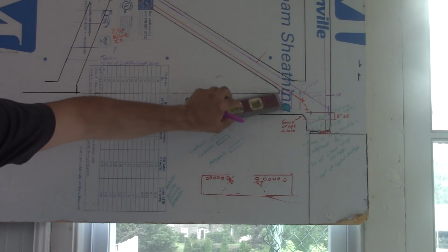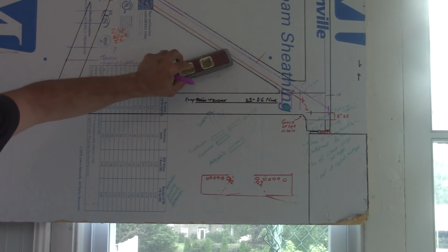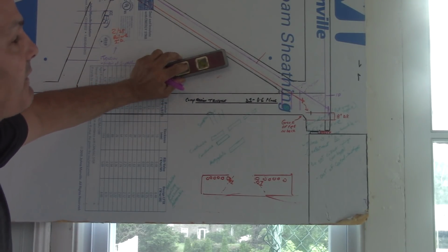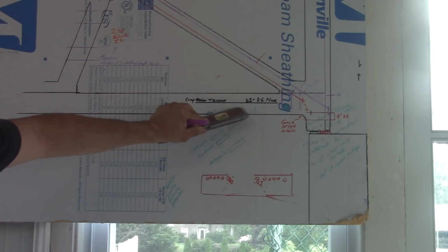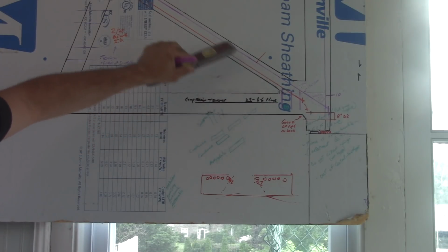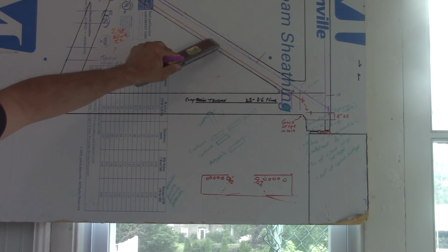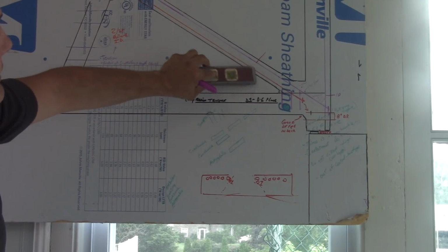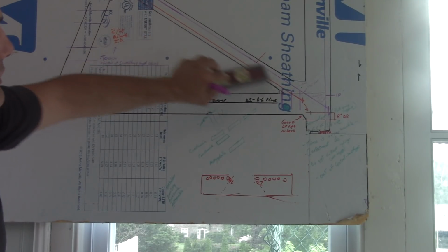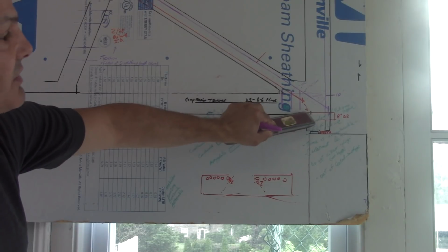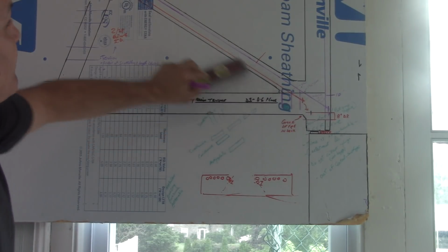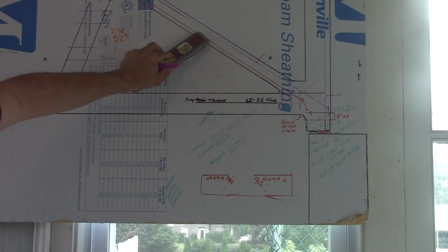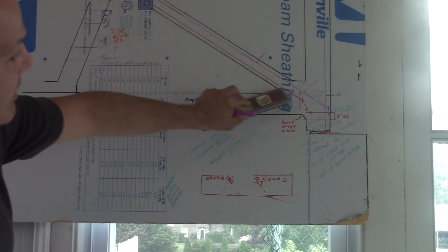When they post-tension this, and you guys know about my other video, the issue is that they took forces off the bridge when they post-tensioned 2 and 11, and then they continued post-tensioning everything else. And at the end, when they put the structure in, they removed the tension off of 2 and 11. That tension was recaptured, I'm calling it, back into the bridge. That tension they took off of it, that weight, was directed back down to here into the, let's consider this an abutment. It recaptured it back into the structure, which exhibited itself in the breaks we see over the next 3-4 days.